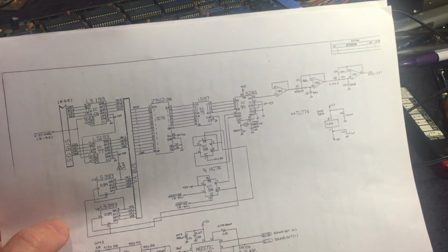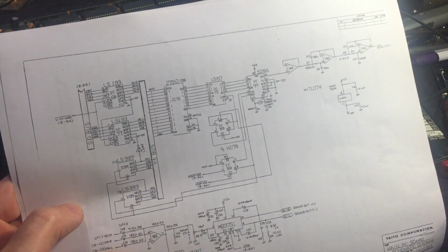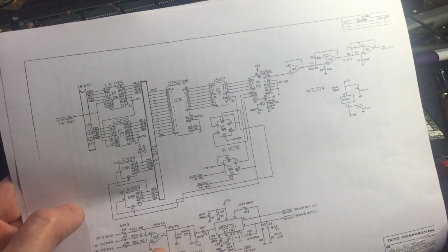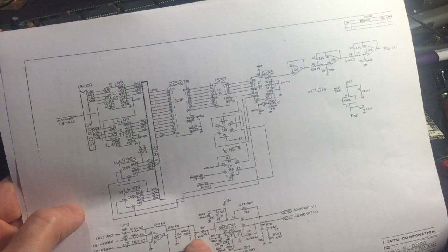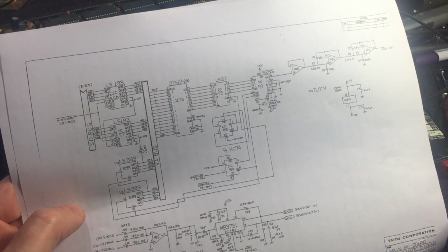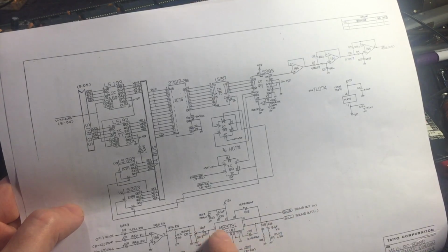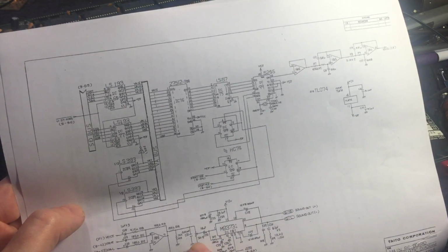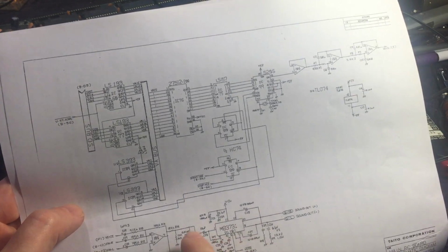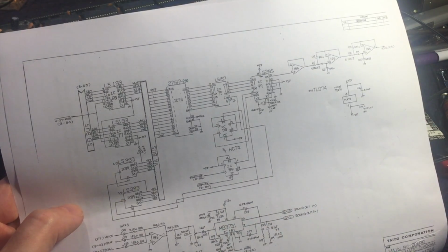And then the FM synthesis from the other page and the voice from the top of this page are combined into this op amp amplifier section. And then there's the volume control and the main audio amp out. So at this point, we are pretty sure that everything from the volume control on is all right, so we don't have a bad capacitor here or anything. Because if I turn up the volume control, I get more background noise, and if I touch the contacts on it, I get buzzing. So the audio amp circuit seems to be good.